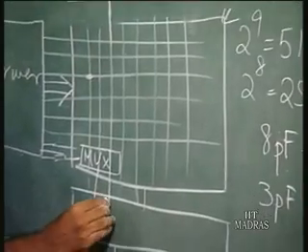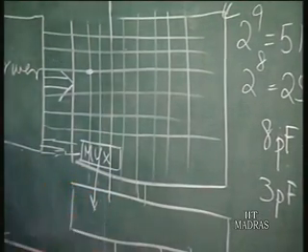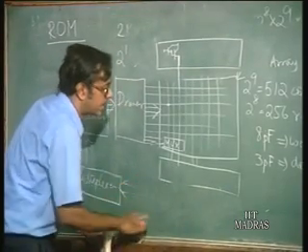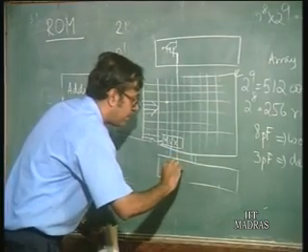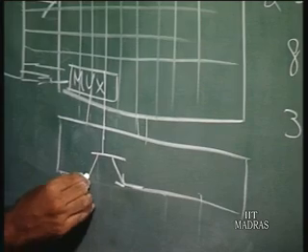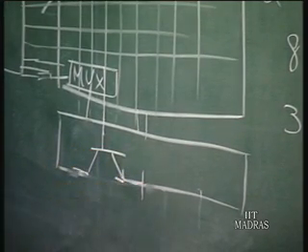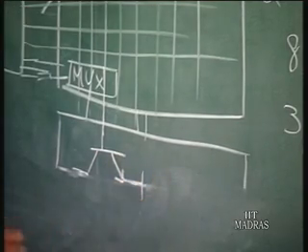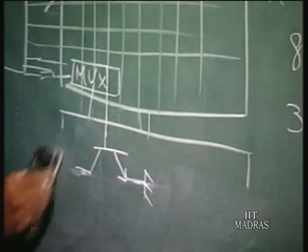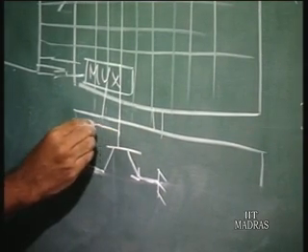And then at this end you have a similar structure just like the previous case, where we discussed the carry chain. You are basically driving a bipolar transistor. I just draw it like this. This is a bipolar transistor. It is coming to the base of a bipolar transistor again, and then again you have as load the MOS transistors, just like the previous case.